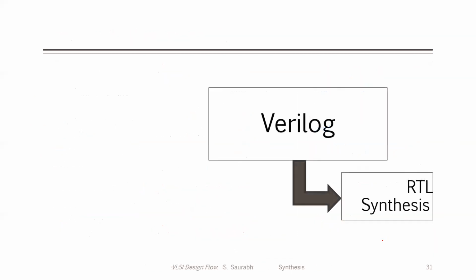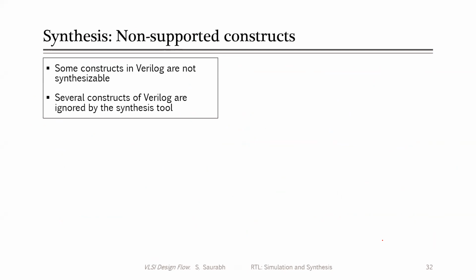Let's move to RTL synthesis. Now let's understand how an RTL model will get synthesized, what instances will be there. First of all, you should understand that some constructs in Verilog are not synthesized. As we started the discussion, we said that Verilog was designed for simulation. It was not designed for synthesis. There are many constructs in Verilog that exist for supporting simulation, but synthesis was developed later on.